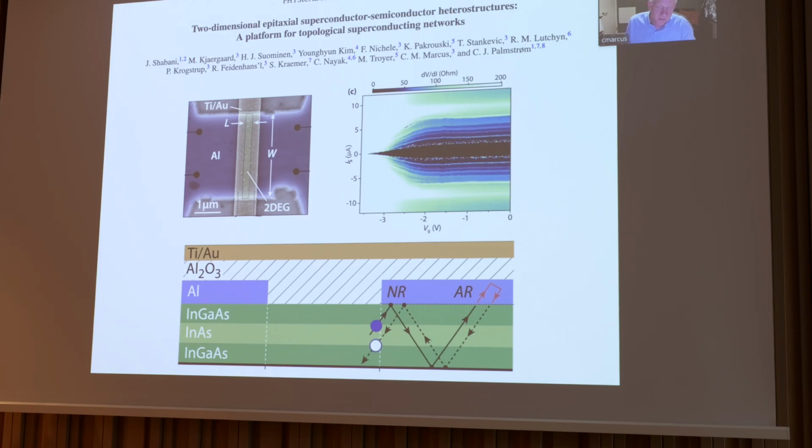than Chris. But the important thing demonstrated in this one slide, and it's really just to represent the kind of emerging literature, is that you can do exactly what you'd hope to do. That is, you can make a superconducting field effect transistor. Here's a junction between regions where the aluminum is left on the semiconductor and removed in this narrow region. The gate passes over the top of the semiconductor. The aluminum has been removed in this rectangle. And just like a field effect transistor, you can deplete the semiconductor and have this look like a transistor.